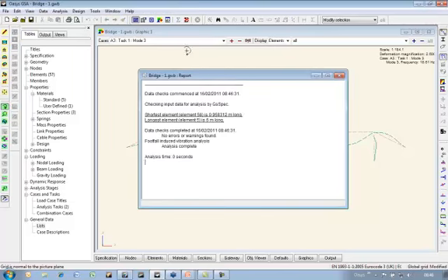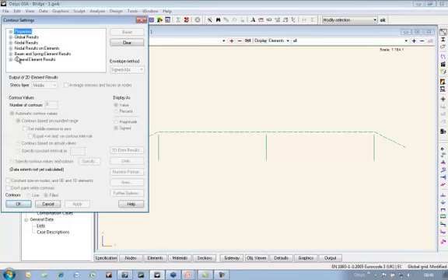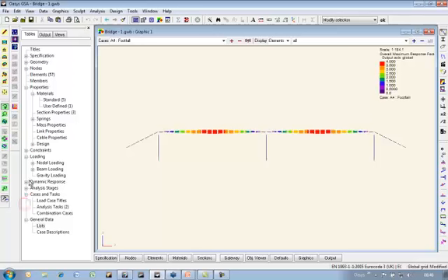We analyze this, and the response that we get. Now, bridge responses can be quite high. We're actually getting a response of about 4, so probably nothing that people will notice at all. For bridges, unacceptable vibrations are over 30 or so, but this is quite a chunky concrete bridge, so this will be fine.